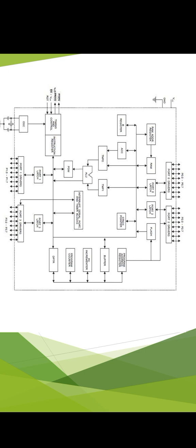Only 21 SFRs are in a typical 8051 family. It is important that the 8051 microcontroller's registers are categorized into 21 special function registers in 7 groups. In CPU registers or math registers, that is A and B registers. Then the PSW status register, program status word, that is PSW. Then pointer registers are DPTR, data pointer, and stack pointer is SP.